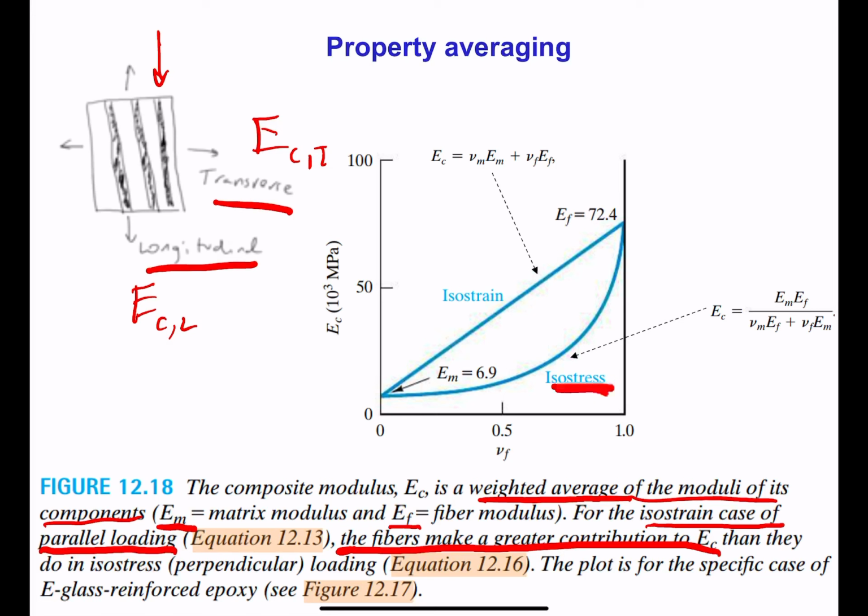And so if one were needing to understand how there was a discrepancy between modulus in one direction versus another, mechanical test work could identify that perhaps fibers are more oriented in one direction versus another, given how the composite was made.